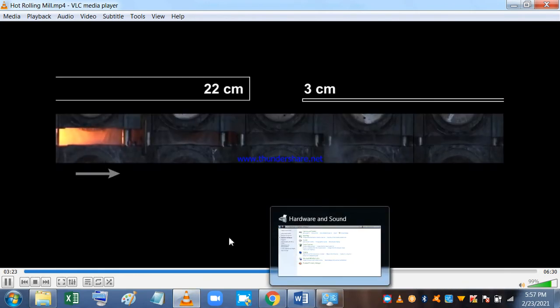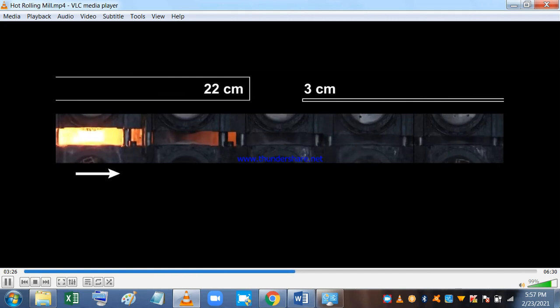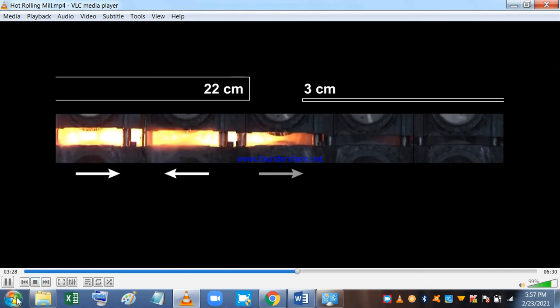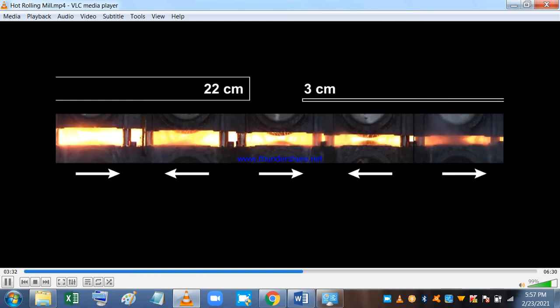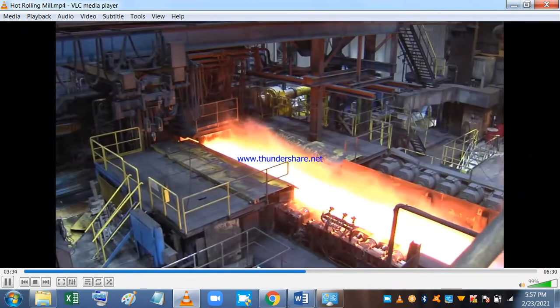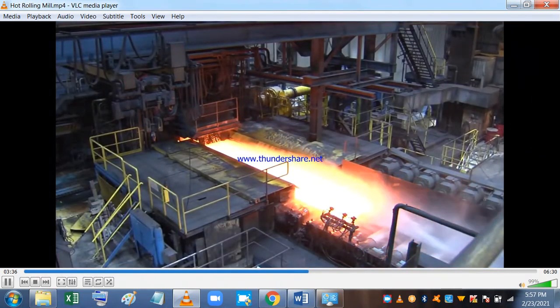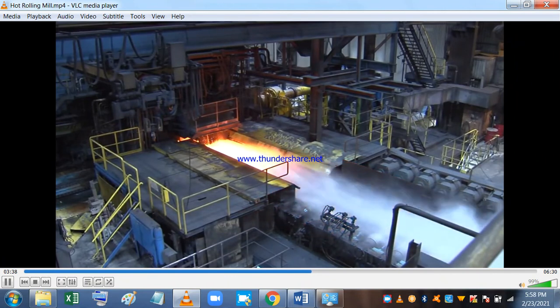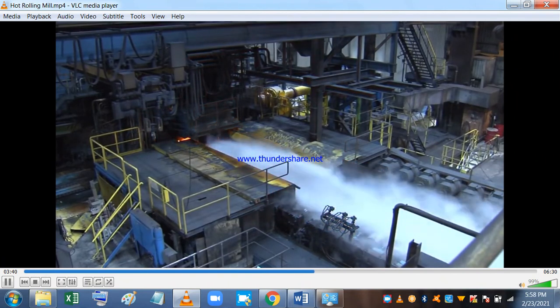This particular material is rolled with 5 passes, where 1 pass means that the material passes through the rolls once. You see the material thickness is reduced from 220 millimeters to 30 millimeters, and through five stages the thickness is getting reduced. The material is surface cleansed several times during the roughing mill process to remove any new traces of mill scale.